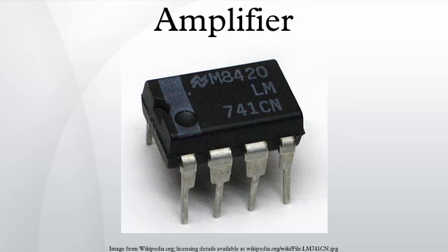Advantages of Class A amplifiers. Class A designs are simpler than other classes. For example, Class AB and B designs require two connected devices in the circuit, each to handle one half of the waveform. Class A can use a single device.